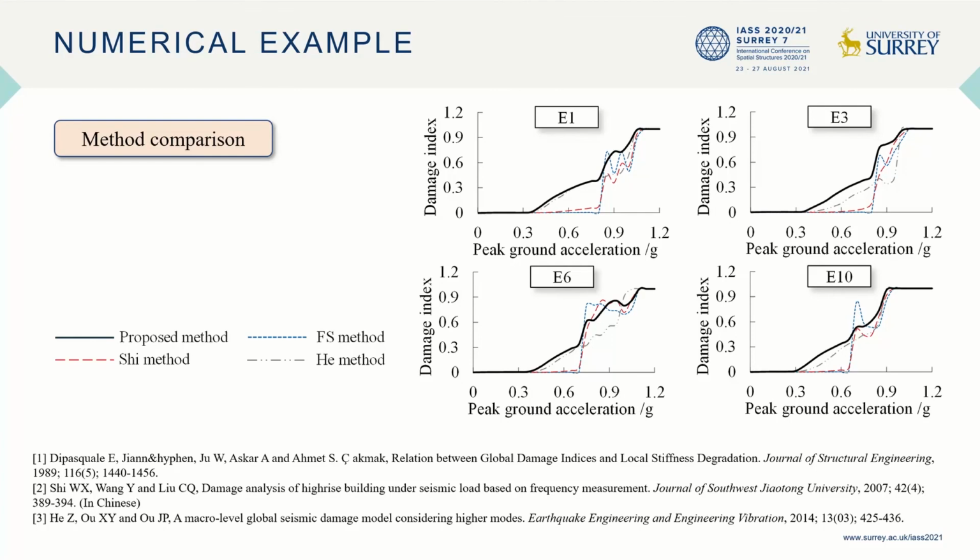As mentioned above, obvious plastic development has been seen in the internal members, and the residual displacement of the earthquake can no longer be ignored, which indicates that it is unreasonable for the seismic damage index to equal 0 in this damage stage.